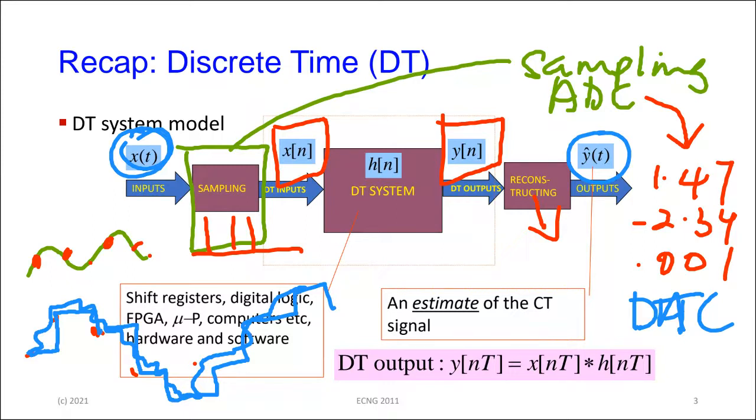Every time you take a picture with your cell phone, this is in fact what is done. The continuous time signal comes in through the lens. The sampling and the converting to numbers is done by a sensor behind the lens, something called, you would probably have met it somewhere else before, a charge coupled device. And each dot on the charge coupled device will produce a pixel or a bit of data coming out. The phone system now will take all of that information that was sensed there, and it will do all of this here to convert it into something called a JPEG.